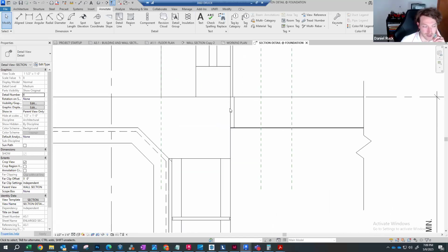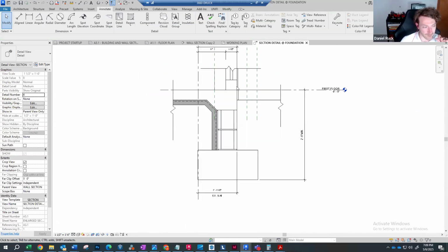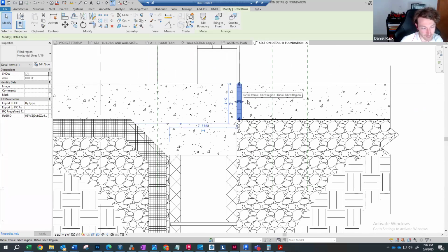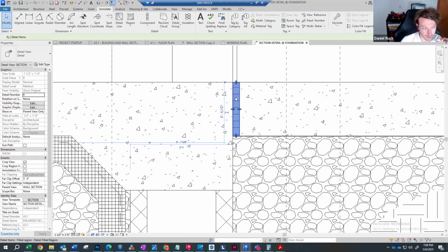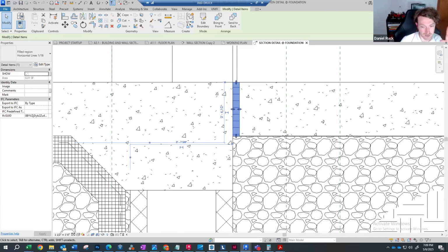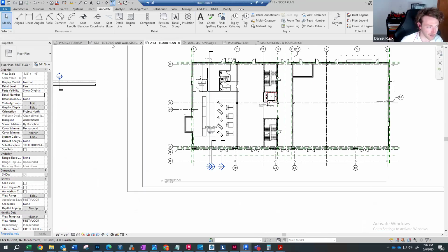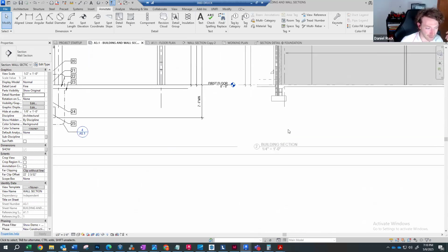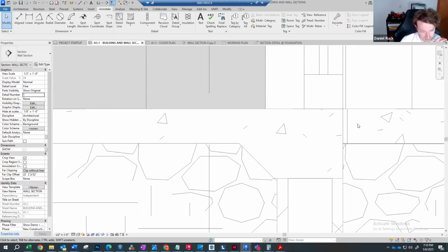So now the building section, you're only gonna see one because this region is relevant to the scale of your drawing. So if you were to copy that same region and paste it in place in your section detail at foundation, you're gonna see more lines, and that's because we have a larger scale. Because we're looking at a wall section or building section that is a 1/2 inch scale and a 1/4 inch scale, you're not gonna be seeing all the individual lines at this condition here.